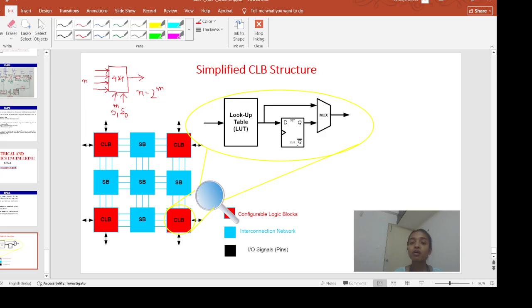In order to make the flip-flop work, we need 2 inputs. One is the normal input, another one is a control input, and Q is the normal output and Q bar is the inverted output. Now here we are giving the positive control signal. This control signal is nothing but a clock signal, which is a digital signal of 0 1 0 1. This means a positive edge triggered clock. The clock we write in short as CLK.